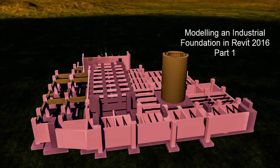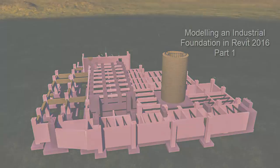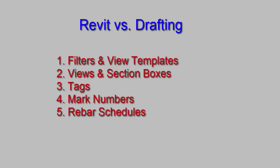In this project, Revit 2016 can replace AutoCAD almost completely. The only exception would be details of anchor bolts and beam connections. For these details, I would use AutoCAD. Using Revit does require a new approach to documenting a construction project such as this. Many former practices were determined by the limitations of drafting. These limitations go all the way back to the age of pencil and paper. The arrival of CAD made drawing lines and making changes easier, but it didn't change much else. CAD, after all, stands for Computer Assisted Drafting. These are the features of Revit that I believe require a new approach to documenting construction information.